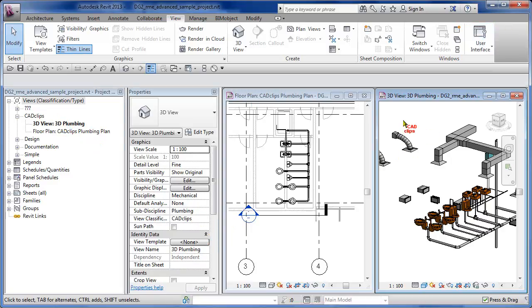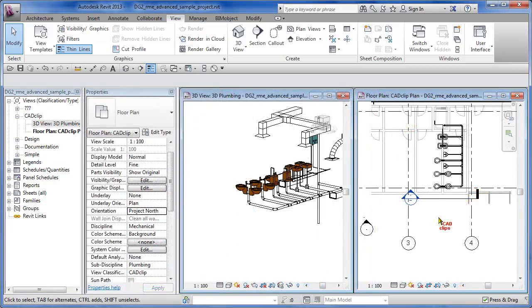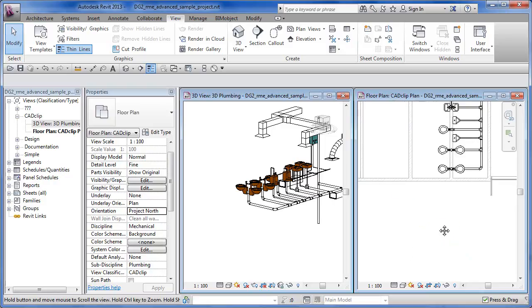my project browser. So now we want to start to draw some pipes in here, and we're going to use a PVC 4-inch kind of sanitary pipe. And we'll start by just drawing flat or non-sloping and vertical piping, just to kind of get the feel for it. So I'm going to pick inside of here and zoom in a little bit.